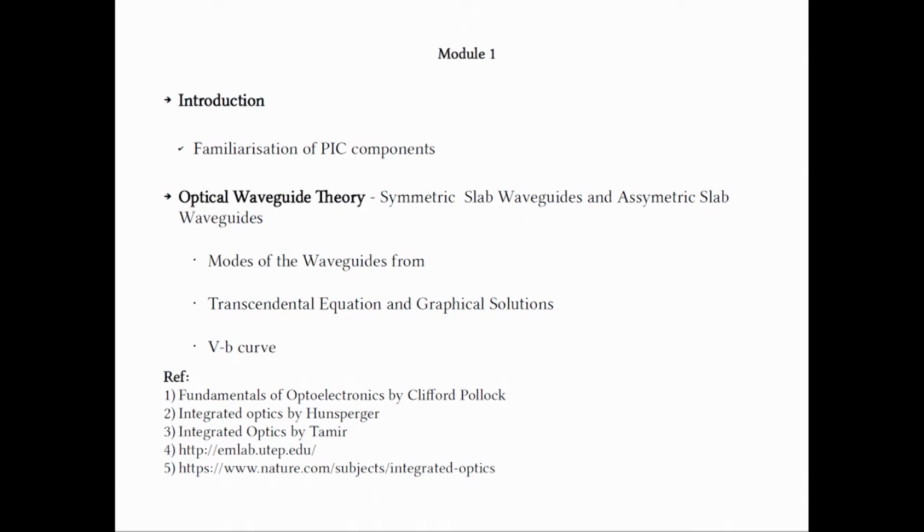In the case of the asymmetric slab waveguide also, we took a parallel approach to that of the symmetric slab waveguide, but of course it is more general, and in particular there is a cutoff V number, below which the light is not guided in the asymmetric slab waveguide. And once again we have seen several properties as a function of the asymmetry parameter and so forth.